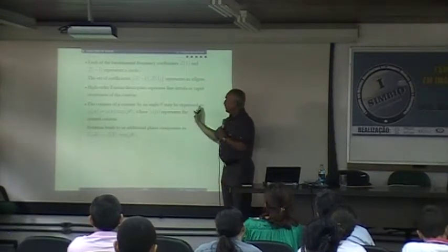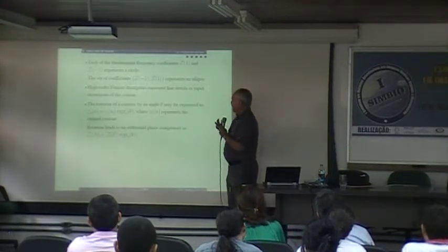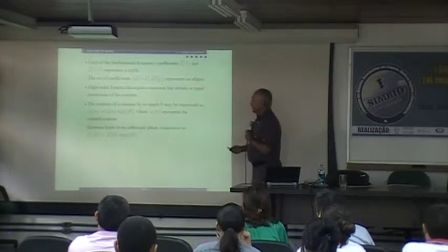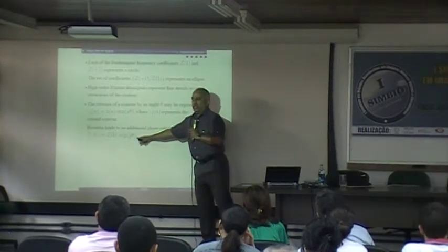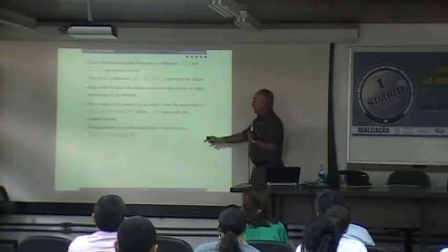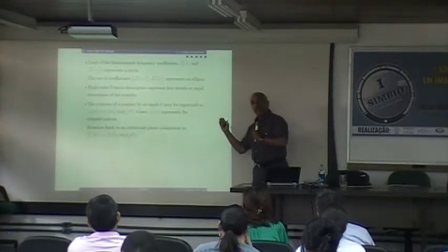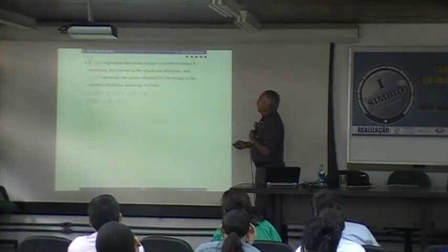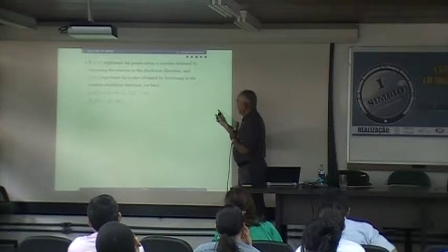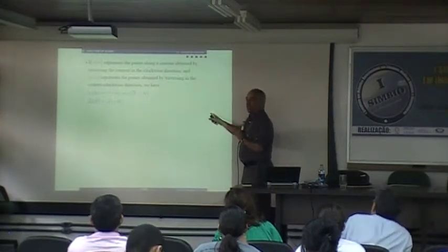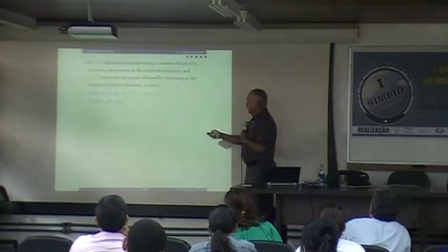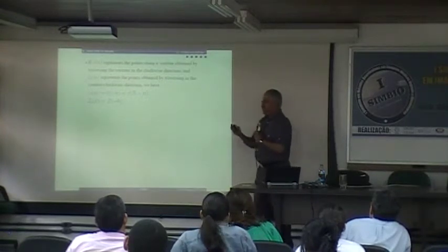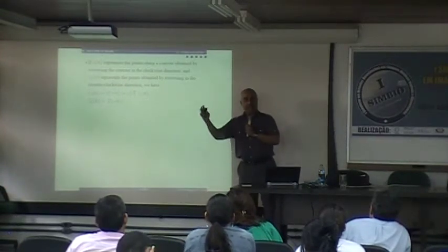You can rotate a contour. This is given, and you can rotate it by multiplying with exponential j theta. And in the Fourier domain, it's the same thing. It leads to an additional phase component. So rotation is additional phase. If you go around a contour this way, you get a certain Fourier transform. If you go the other way, you get Z minus k. Zk and Z minus k will be switched. The spectrum will be switched from positive to negative or negative to positive.